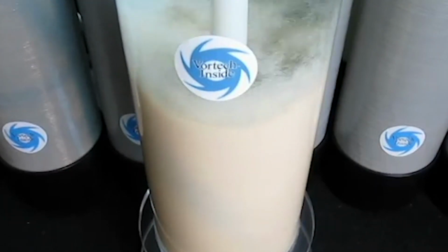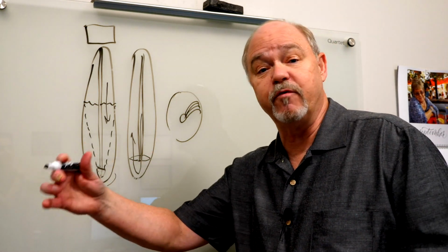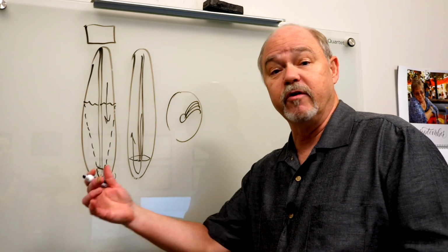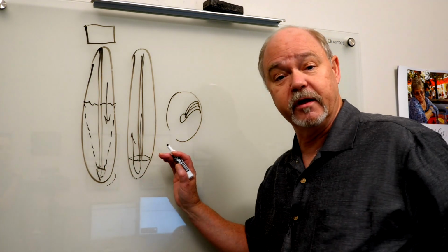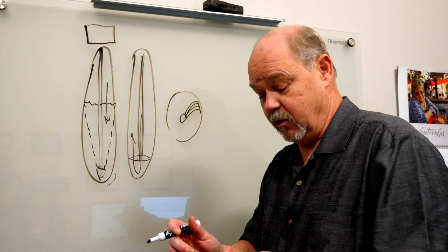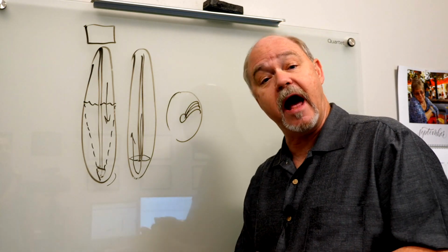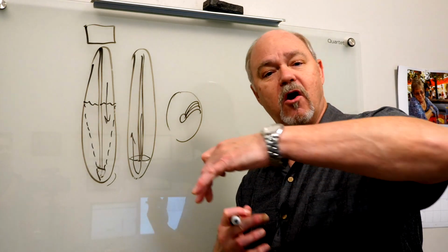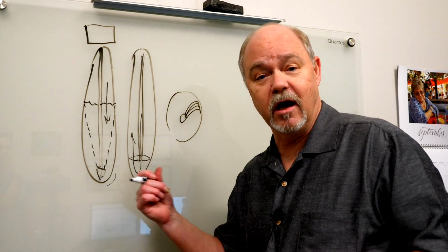The benefit of that is it eliminates the backwashing cycle because the media is always in motion. So we don't have to lift the bed, because we don't have media that's not seeing water flow. The other benefit is we're not going to dispense 30, 40 or more gallons of water to the drain every few days just so that we can stir the media up. So the upflow benefit is that we don't have to backwash, we don't have to run water to the drain, and we actually gain efficiency and better contact with the water because of the media always being in motion. We get better pH adjustment. That's the reason we like the upflow tanks.